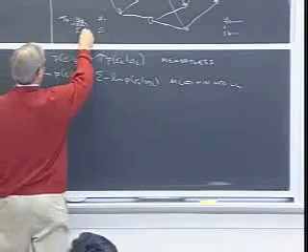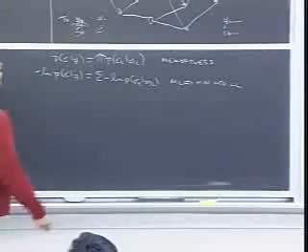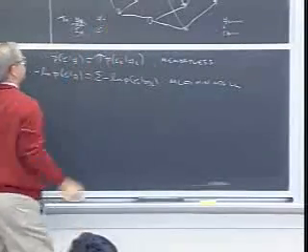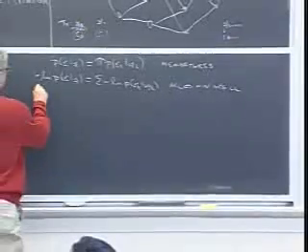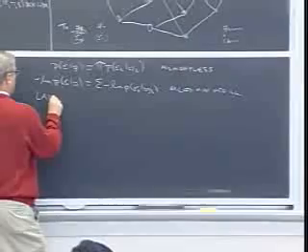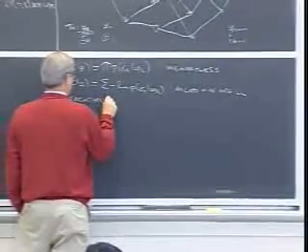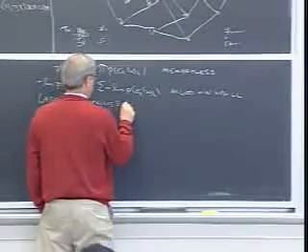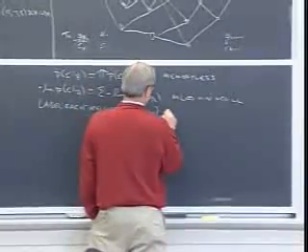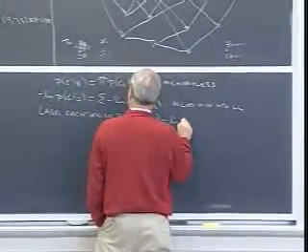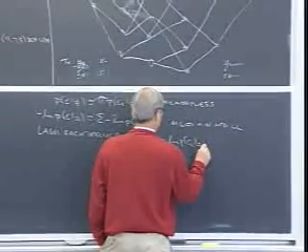Okay, I receive only one thing in each time unit, and each trellis branch corresponds to transmitting a specific thing. So I can label each trellis branch with the appropriate minus log P of Rk given Yk. Do you see that?